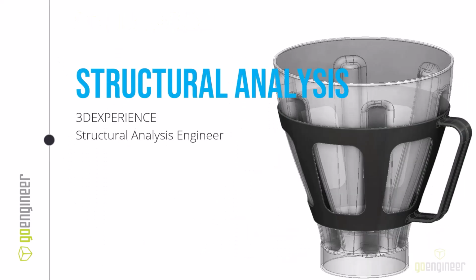Let's look at the pitcher handle. The handle looks stylish, and our intuition indicates it can withstand a large load, but we do not want to move up to a prototype before we confirm the handle can withstand 25 pounds of product in the pitcher. It's way more than what we would normally expect. We know we need to stay below a stress of 1200 psi to keep a factor of safety of 2 or better. Let's see how the handle performs.